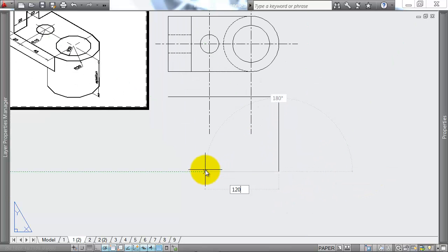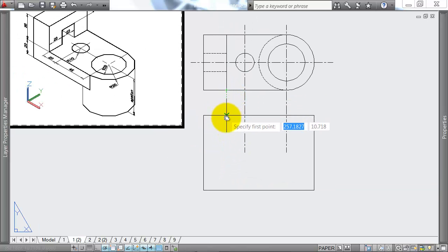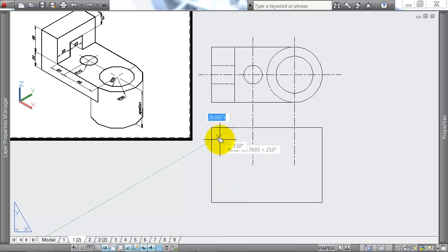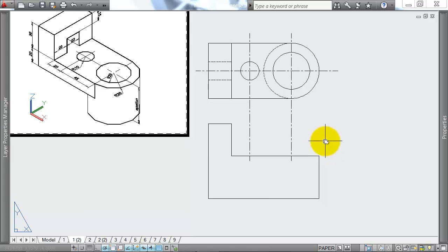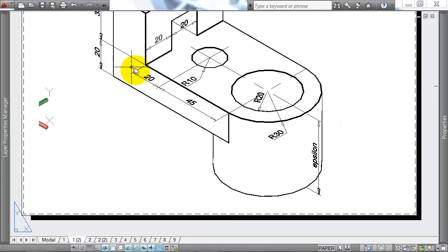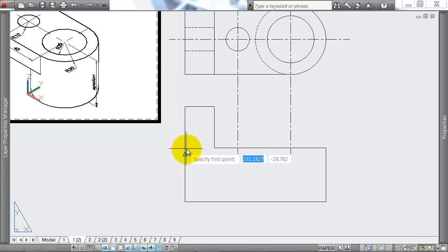And across 120, close. Now in line with this edge, coming down a height of 35 units. I've got that first part of the feature. This one will run the whole way across. I now don't need that. The height of this strip in the middle, the table part of the shape, is only 20 units. So I can run another line which is say 20 units down from this one.